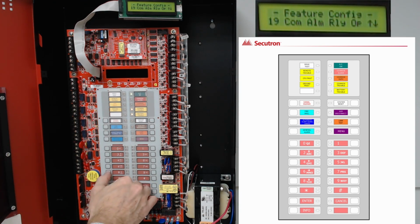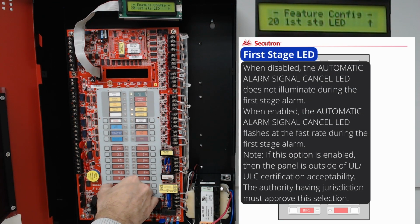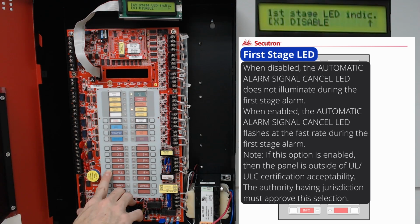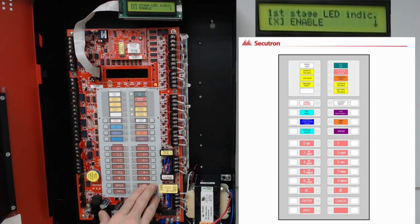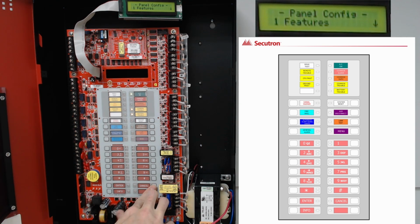Our last option under feature config is first stage LED. By default, it's been selected as disabled. If we want to enable our first stage LED, we'll hit the up cursor arrow and then the left or right cursor arrow to apply the X to enable. Again, if we hit cancel, we'll exit back out to the feature config options. By pressing cancel again, we'll exit back out to the panel config.